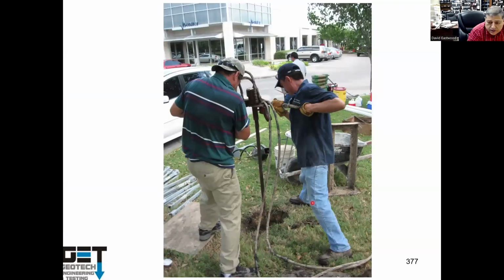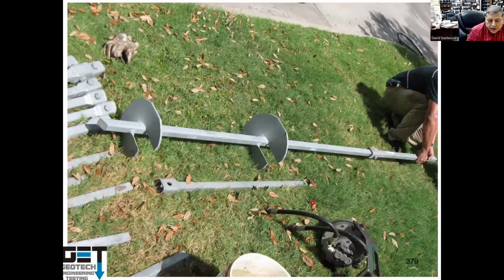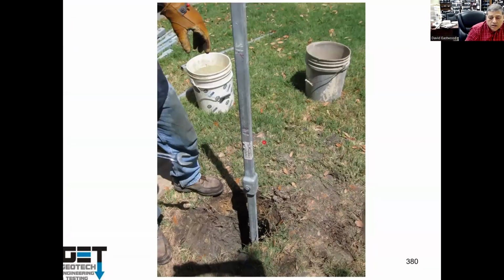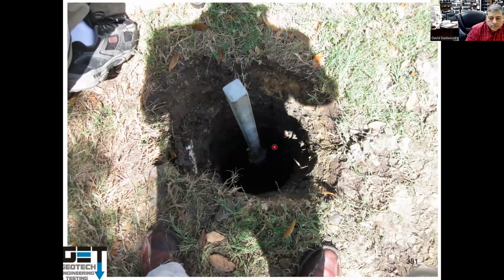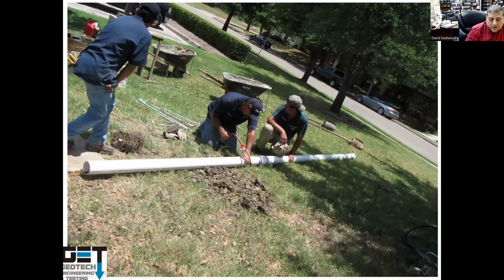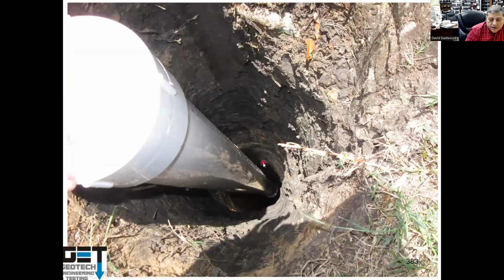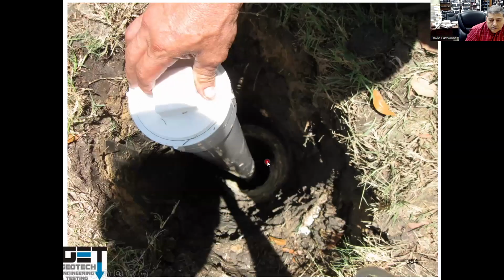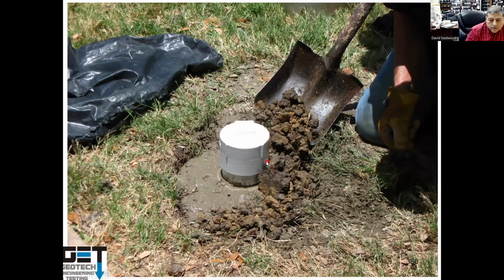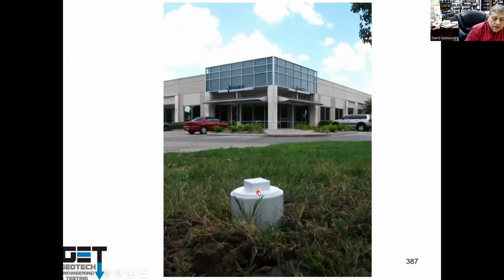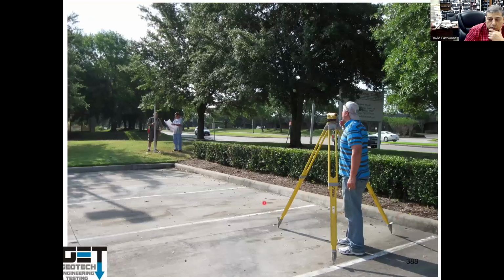If you want to know exact movements of a building, you put a benchmark into place. A benchmark is a fixed point that doesn't move. So you dig a hole in the ground about 20 foot deep. You drill the hole, you put helical piles in it, down about 20 feet. This is the pile, it's connected to the soil at 20 feet. It's not in connection with any soil around it. Then put PVC around it. Then you fill in the area between the PVC and the soil with grout. This becomes a fixed point that's connected below the active movement zone. So it doesn't move, so you can use that as a benchmark here to measure elevations around inside the building.